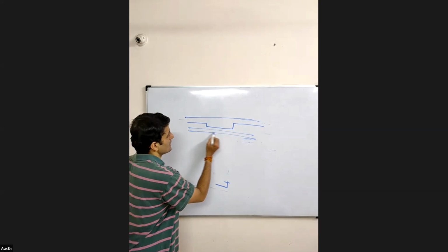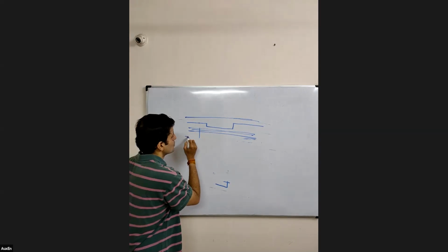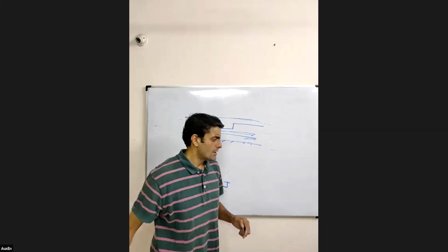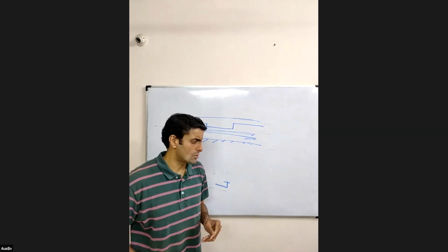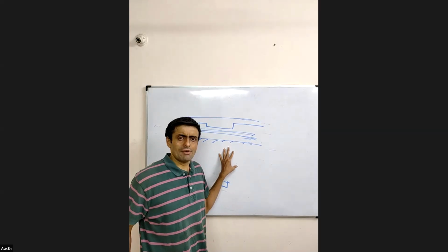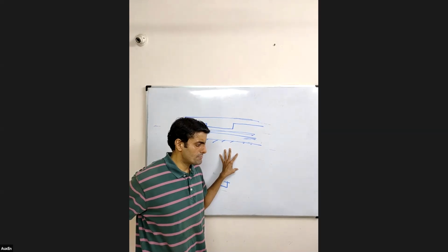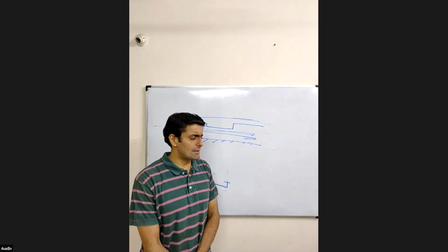My service lines very easily pass right through it, and then I can provide a false roofing arrangement. In such a way I am able to manage my service lines also. So this is the second advantage, and I would say a very important advantage of having a flat slab system.